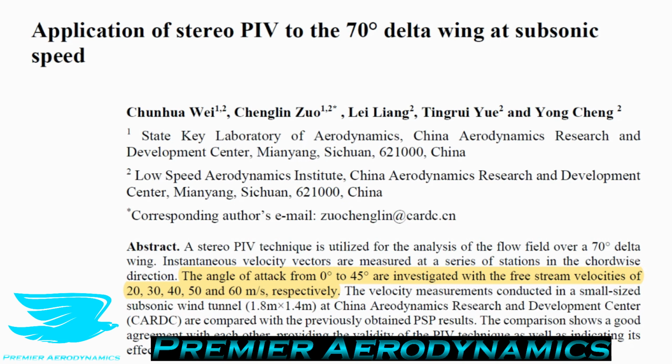Then these particles are going through the flow, and then you shine a sheet actually through the flow at whatever position you want to determine what the velocities are. So let's say you have an object, a ball, and then just behind it you'll put a laser sheet, and you want it to be very thin. The reason why is because the thicker the laser sheet is, the more corrupt your velocities will be.